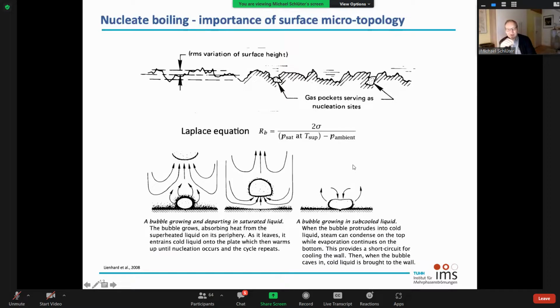What happens, and you're totally right with that, is that due to the missing nucleation sites, the temperature increases and increases and increases. So we have a superheat of, let's say, 10 to 20 degrees Celsius. It's quite strange. You can measure the temperature in your pot, and the temperature will be at 120 degrees Celsius. And despite you have 120 degrees, you still have no cooking. So everybody is telling you that water cooks at 100 degrees, but without any nucleation site, you will not have this cooking.